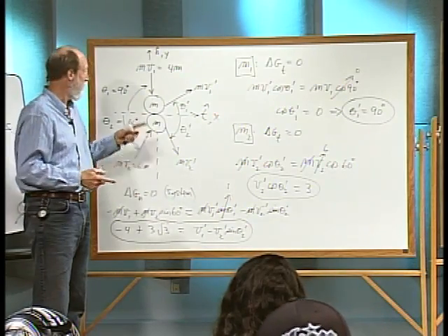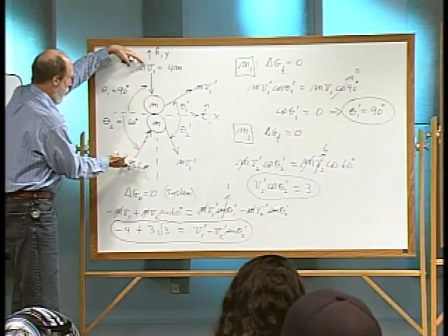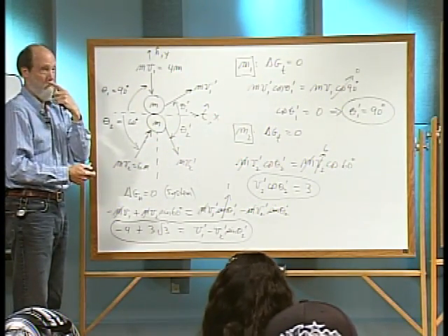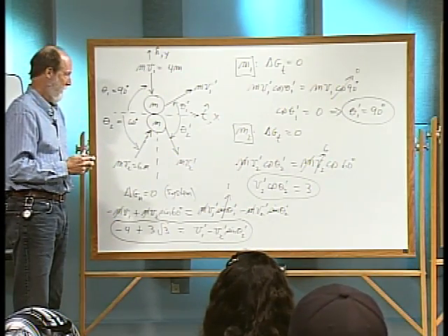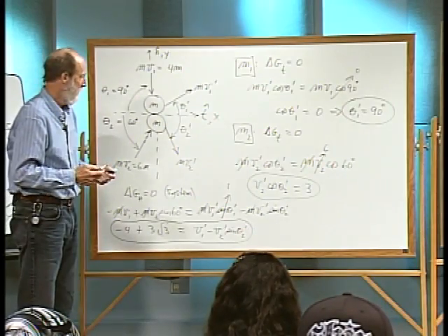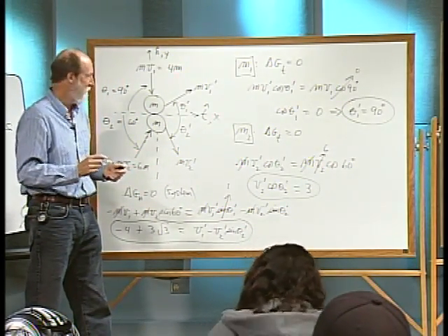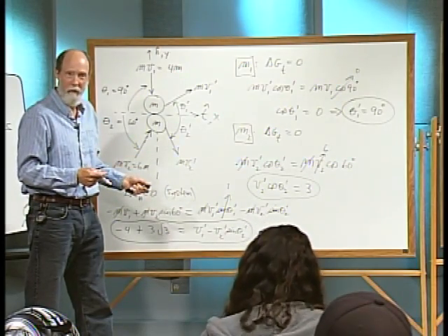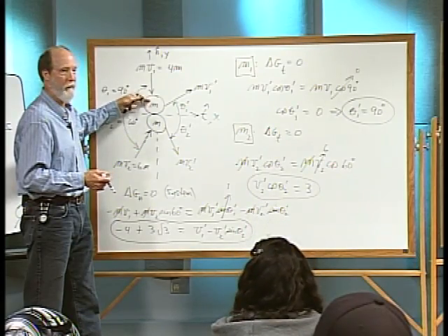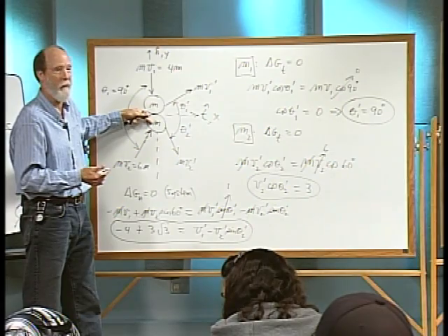In the general situation, showing the incoming angles, different 2 velocities, and outgoing 4 items, you typically have 4 equations. Okay. So anyway, we have 2 equations, 3 unknowns. Okay, got to say that right. So we need another equation that relates to the materials that are interacting with one another. It happens to be steel on steel, which I believe they said was 0.6 for the coefficient of restitution.